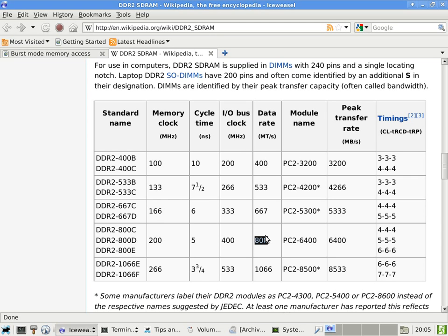In other words, this is a perfect square wave, which is what we want on a motherboard. With inductance and capacitance, it's not going to look like this. It will look more like this. Ring a little bit, ring a little bit, like that. So depending on how much inductance you have and how much capacitance you have, the shape of the perfect square wave can be way off. Now, what can be worse than way off? Different lines are off in different ways. That would make it even worse, because now it is really hard to match up all the lines that you need in a parallel bus type of architecture. So that's another reason why they went from parallel back to serial.